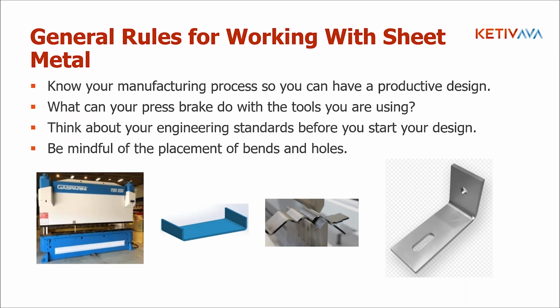The other thing to know with sheet metal is there are some standards working with sheet metal with parts. You don't want to put holes or features too close to bends or too close to the edge of the part, because then you can have a part that will fail. So just be mindful of your company's standards or industry standard for sheet metal when you're designing your part.